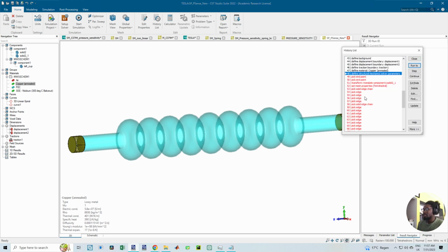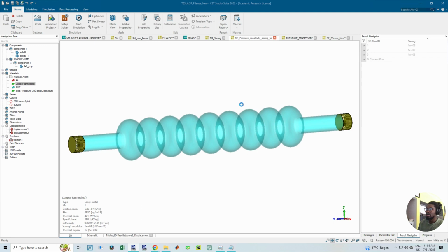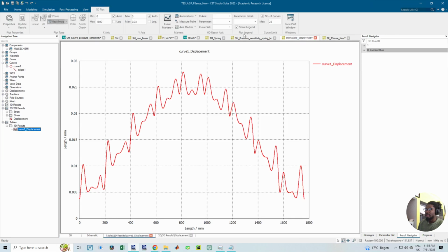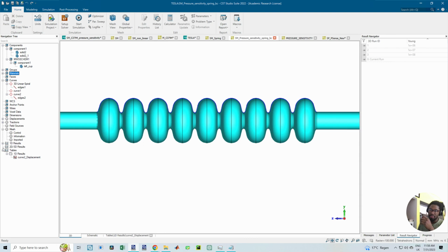Yeah, then I define the parameters for the structural analysis, and I think I could show that. So again, not very detailed. I didn't do any adaptive mesh. I didn't apply any non-linearity. Of course, we are not expecting large deformation, and then the accuracy I reduced to 1e-6. So these were the settings I applied, and then ran the simulation. After the first run, I got the displacement and stress and all the results you typically have.